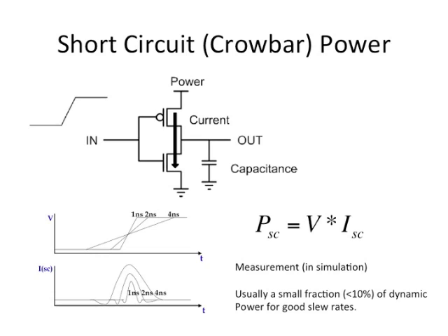It's a short circuit. So the current goes through both of them, right? Here, if you are looking at the power drawn from the battery, then when I am discharging the output capacitance, the current from the battery is just there to supply the short circuit current, because the current from the capacitor is going directly through the NMOS, right? So if you are looking at that current, the question is, will the peak of the current change as I am changing the ramp rate?